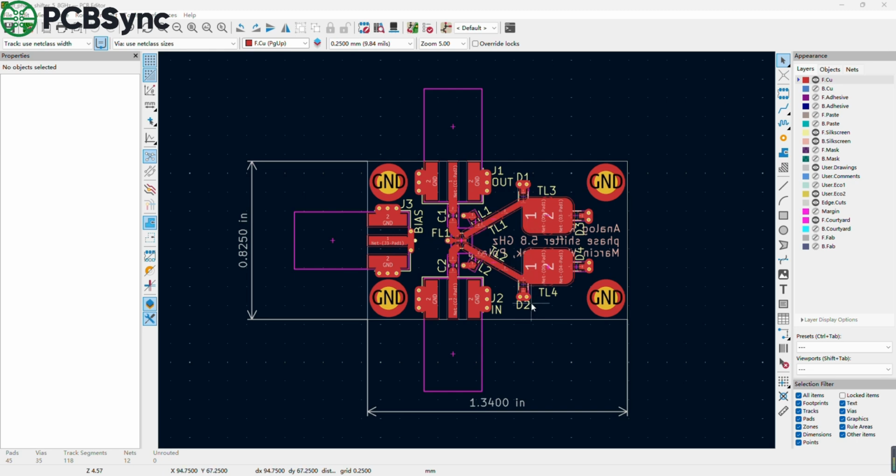Because RO4003C and RO4350B have different design dielectric constant values, the same board layout can't be directly swapped between the two materials. If you change RO4003C to RO4350B or vice versa, you need to recheck the dielectric thickness, trace width, transmission line length, and matching results. Choosing high-frequency materials isn't just about changing the material name, it's about reconfirming the entire stack-up and electrical dimensions.